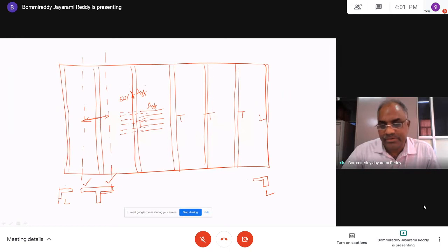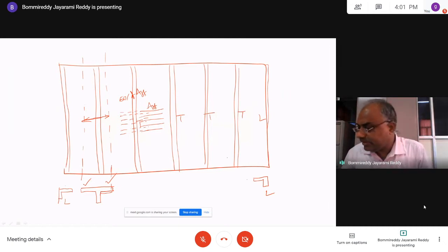That is one condition. Another condition is that the area of the reinforcement designed for the slab is AST, and at least 60% of that reinforcement is to be provided at the top of the beam, so that it will act as tension reinforcement. These two conditions are to be satisfied, then only it will be called a T-beam.